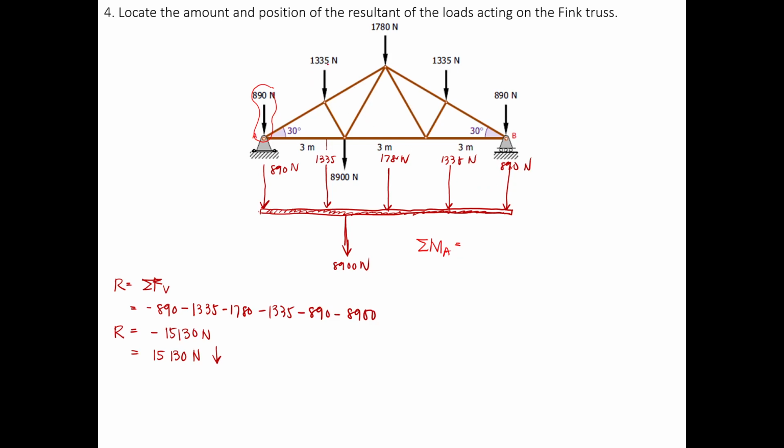So next is your 1335. This one is point A. So that's negative 1335 because we will have a negative moment, since the rotation is clockwise. The distance is yet unknown, right? This is an unknown distance.